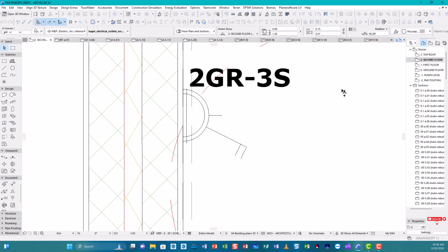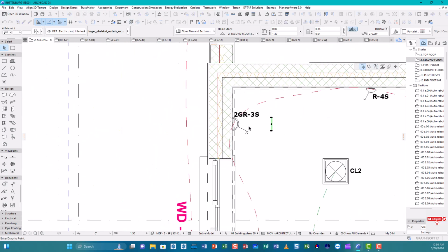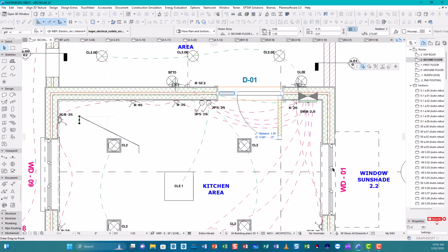Click down. I have a copy here because it's to be to the opposite side from the back. So which means I will have to mirror it. I'm going to click on one node there. Then I'll say mirror. Either you go Control M, you'll be able to mirror. So I'm gonna mirror it this way, right? Then I'll click on one node there. We go drag, zoom out this way, come all the way here.